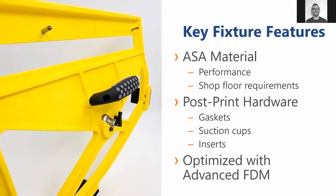We were also able to leverage, a little difficult to see down in these bottom corners here, our alignment features for in the door gaps. Those were nylon 12CF just to afford the utmost strength and stiffness, so we didn't see any flex in this tool. We, of course, have optimized this for hardware installation. So we have handle inserts, peg inserts, suction cups with proper mounts, as well as the hardware that was embedded into this part to allow for these placement, these black locating features to be added on afterwards.